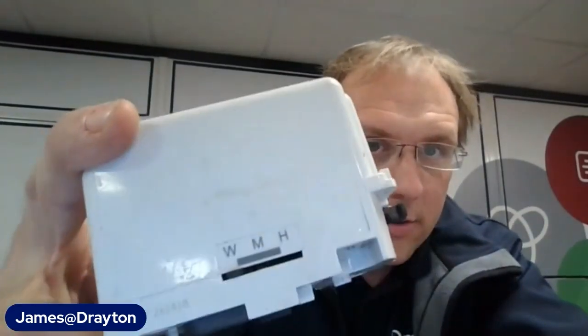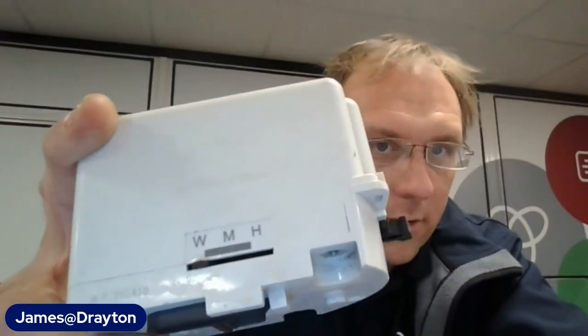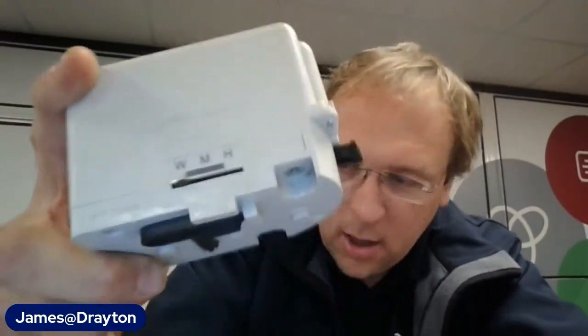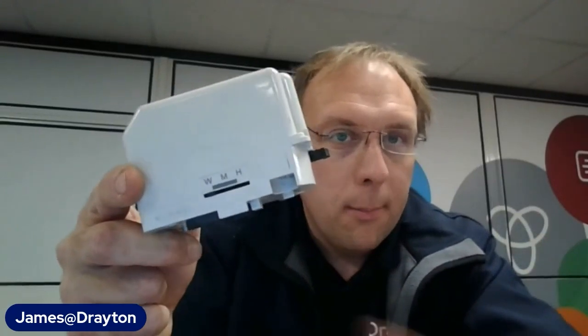So this here is a mid-position actuator. You can see it looks pretty much the same. This one's a little bit used, I would say. But this has got your water, mid, and heating. So this is always going to be supplied on a 3-port body. It's nonsensical to put it on a 2-port because if it sits in the mid position, you've just got a 2-port that's slightly less open than it would be. So this will fit on a 3-port body. You'll feed up the leg of the T from your boiler, and then you'll divert through ports A and B to central heating and hot water.